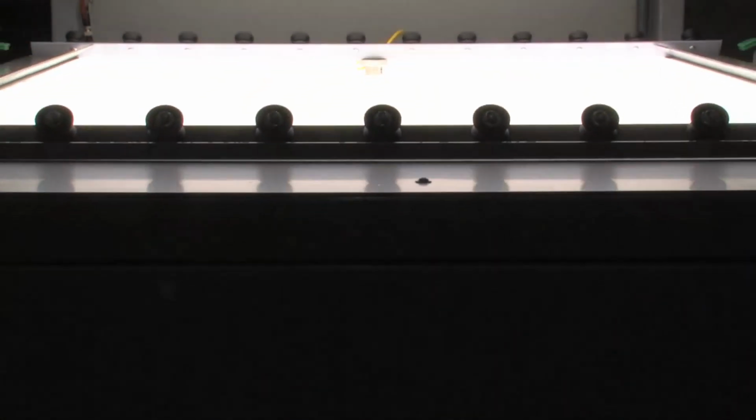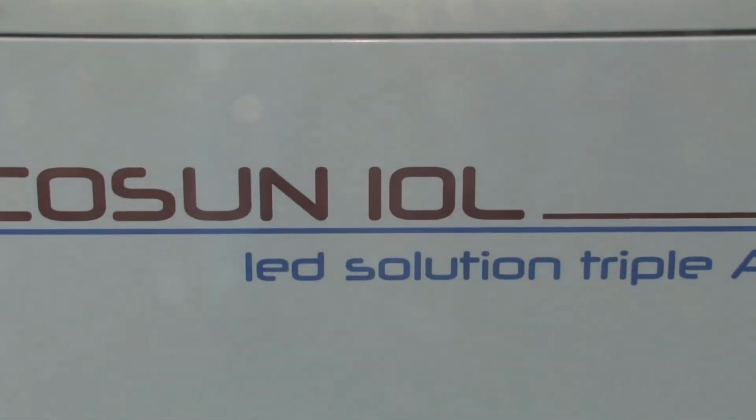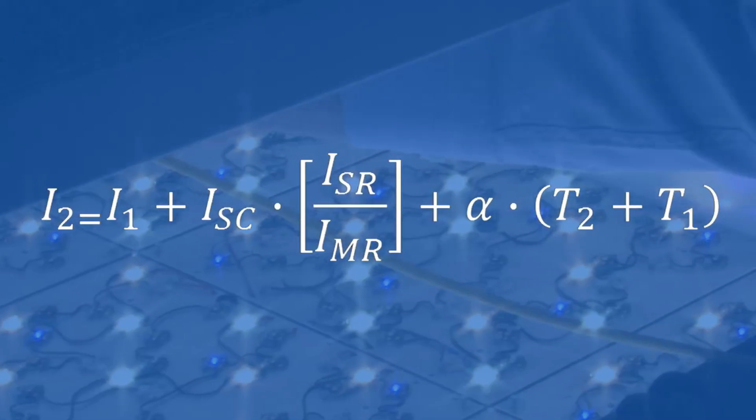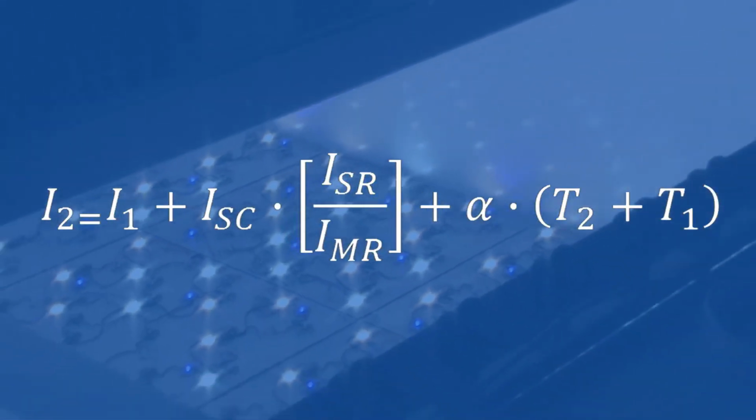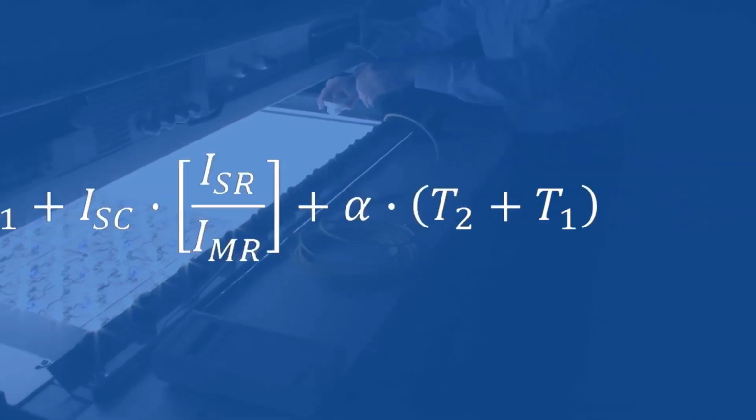The system, more than gathering the electrical data of the module, acquires also information regarding the temperature and irradiation. In particular, the system registers the module temperature, the ambient temperature, and the source temperature. Like this, it's possible to obtain a complete vision of the test conditions. And with this information, the user can proceed with adjustments according to the norms in order to calculate the normalized values.